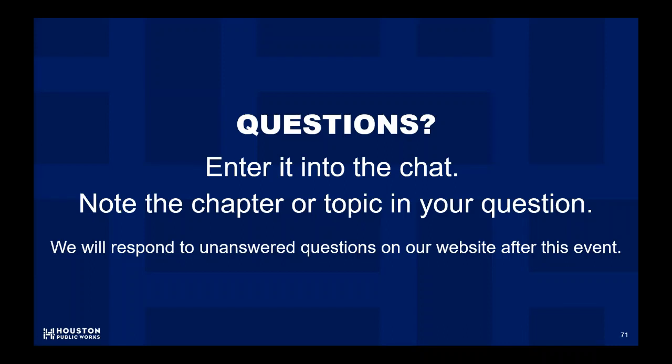Brian, I don't know if you had anything to add to that. Just unmute here. Yeah, I think lane widths are determined by referring to your funding agreement and the documents that go along with that federally funded project. There are a lot of conversations that do go on about other items. If you're building a city asset, the city is going to ask that you follow city standards most of the time, but that unravels a conversation between TxDOT and the city on that project.